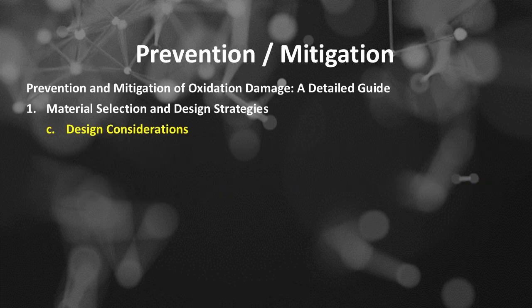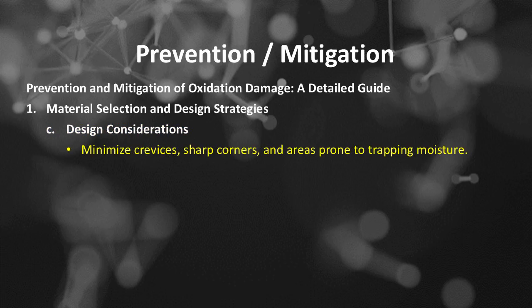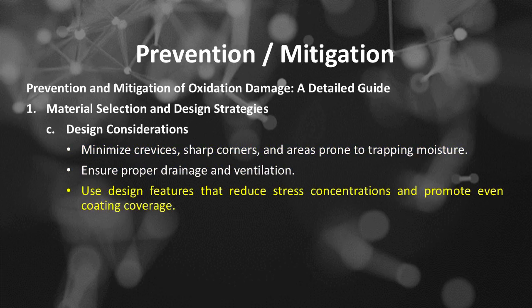Number C of material selection and design strategies is design considerations. Minimize crevices, sharp corners, and areas prone to trapping moisture. Ensure proper drainage and ventilation. Use design features that reduce stress concentrations and promote even coating coverage.